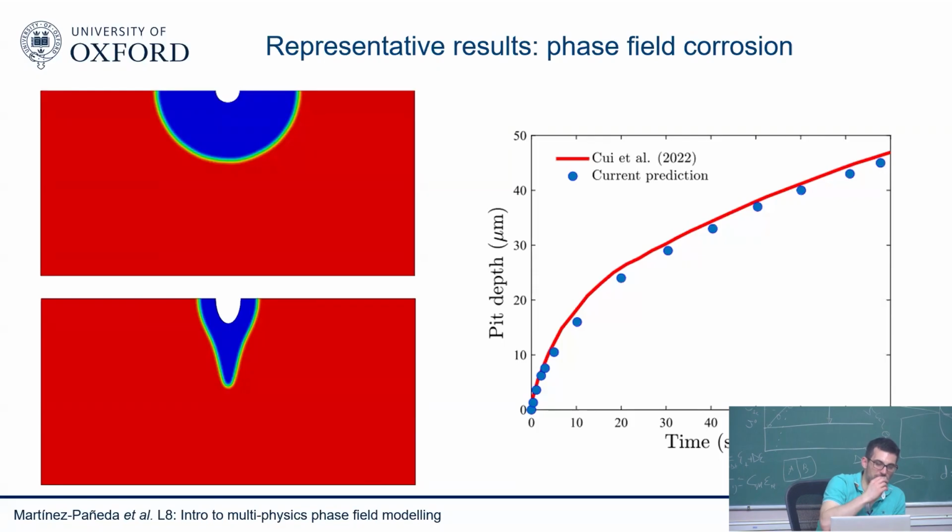The same step is defined for all cases, so you cannot uncouple step jumps. You cannot just say, oh, this one is going to take much bigger steps than the other ones. You will still need to have a fully consistent backward Euler method anyway. So I think you are limited to the smaller steps for the problem that you need to solve. If the fracture requires small steps, you're going to have to solve the hydrogen transport in small steps, which is kind of what will happen in reality. You need to resolve what the phase field hydrogen is doing as the crack grows and things like this.